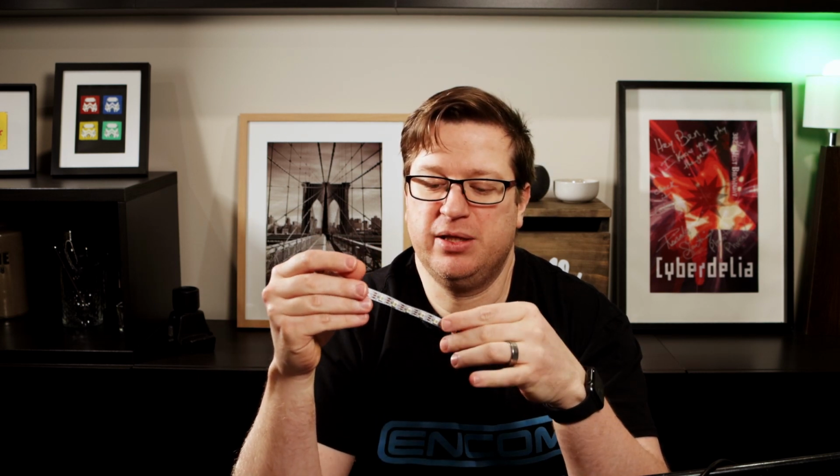Now, despite the problems that occurred during the setup, I am really happy with the results of this test. I'm waiting on some more LED strips to arrive so that I can set them up on the new TV, and I'm definitely looking forward to watching some movies with those reactive bias lighting LEDs set up. Something I probably will do next time is use a logic level shifter on the output of the GPIO pin to make sure that the voltage that's going into the logic input of the LED strip is enough to make sure that it's actually doing the job properly.